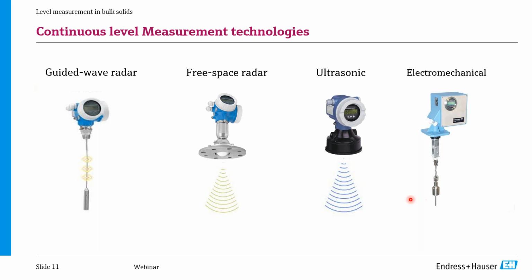All right. The ultrasonic measurement was for a long time the primary method used to monitor the level of solids, and is still today a very cost-effective solution, especially in very small ranges. But today we'll give a very special focus to the free space radar. Especially because there have been several improvements in the technology regarding signal processing and different operational procedures that now allow us to use this principle as a reliable resource for level measurement in solids.